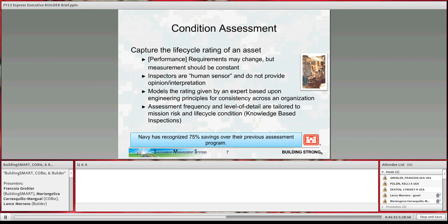If I'm up on a roof, I'm going to look for ponding, seam tears, blisters, and where the flashing is separating from a penetration or from the parapet wall. And then the system has all of the engineering data to say, from a life cycle perspective, this puts you at 10% of its remaining life, or this puts you at 80% of its remaining life. So the system can objectively determine where the component is in its life cycle.